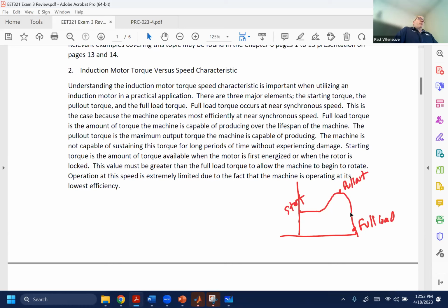And the reason why you don't trip it out on 5 or 10% is, is that really an overload, or is that just a mismeasurement? Remember, if you look at protection for devices, usually protection is for tripping of the device. So you have a lot of current going to it, you've got a problem, we've got to take that offline. But overload conditions is somebody put the wrong piece of equipment in there. You screwed up your design. That's up to the operator to go out and say, hey, that motor's getting pretty hot. We better go out and trip it.